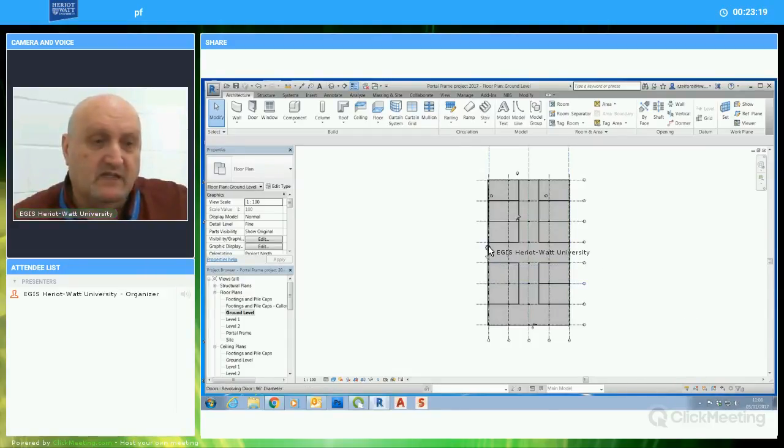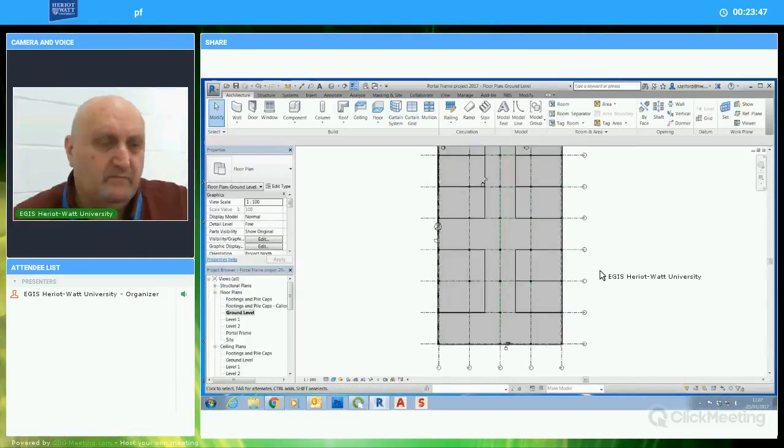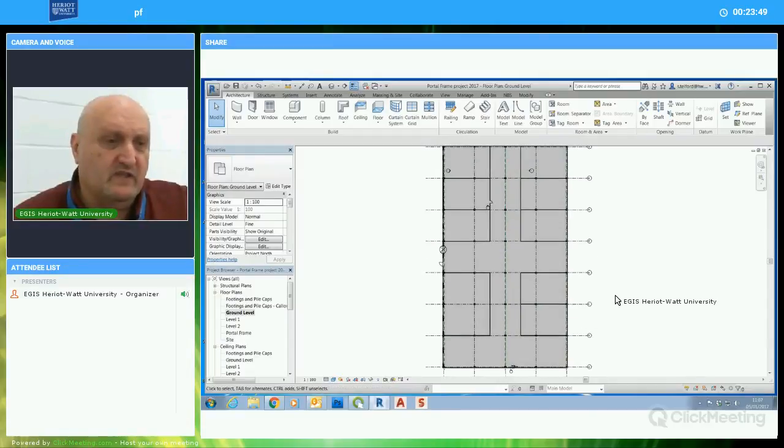The exterior doors have got to open onto the horizontal circulation space. You can't have this door opening onto some private office. This is going to generate a footfall in a commercial building, so it's going to allow people to enter and exit the building, and you don't want them coming into some private office or private shop. You want them to come through this public access area, like the central part of a mall or whatever it is, central corridor if it was just offices.